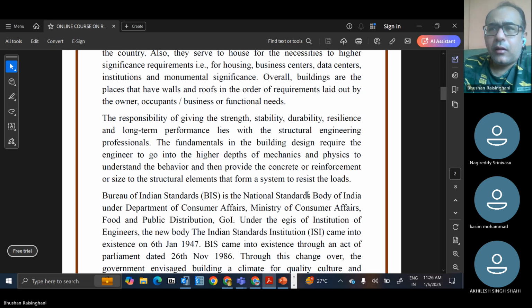Many people are releasing the elements in RCC, like beam release for torsion, and beam release for secondary beams. Even if the secondary beam is of 600 depth, it is released, on the understanding that the detailing is such that we will not fully connect the reinforcement with the main beam. So the secondary beam can be taken as simply supported, and we will release at the ends where this secondary beam is connected with the main beam. However,